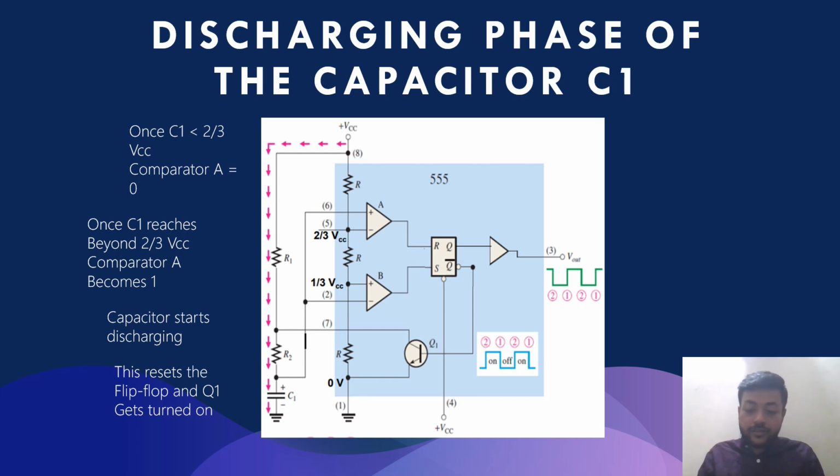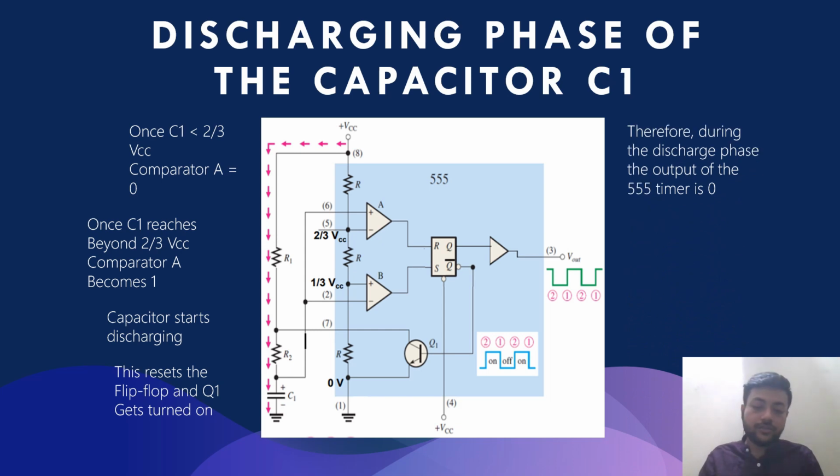Registering and counting oscillation. As C1 discharges through R2, the voltage at pin 2 falls. When it reaches another threshold, one-third of VCC, the 555 timer's output flips back to high, recharging C1. The cycle of recharging and discharging C1 based on voltage thresholds at pin 2 continues, creating a continuous stream of square waves at the output at pin 3.